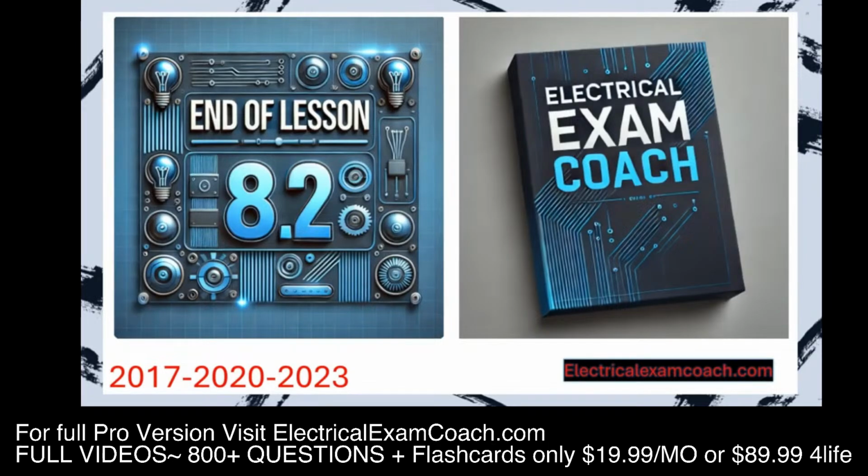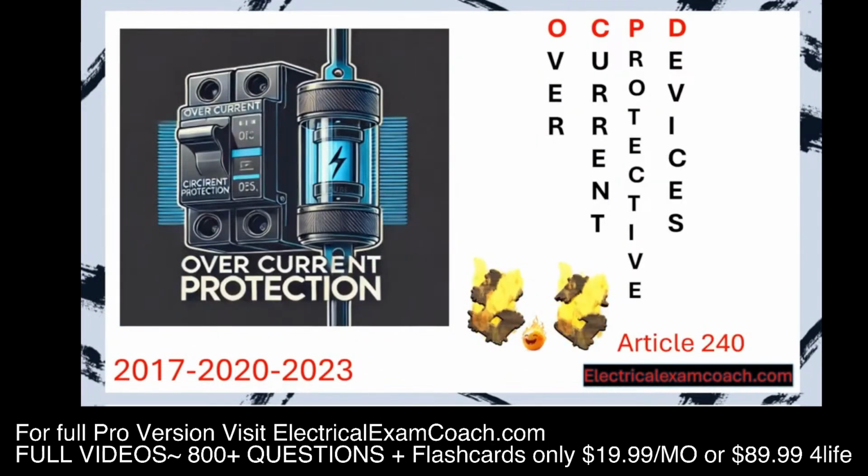Hey everyone, welcome back. I am the Electrical Code Coach from electricalexamcoach.com, and this is lesson 8.3 in our video series. We're still in Article 240, but we're going to be doing sample calculations of whole homes and businesses and selecting the main overcurrent device. Learning how to take all the work that we've done in the program up until this point, the load calculations and everything, and then take those total VAs and find out how to choose that overcurrent device, which will ultimately dictate the size of the service.